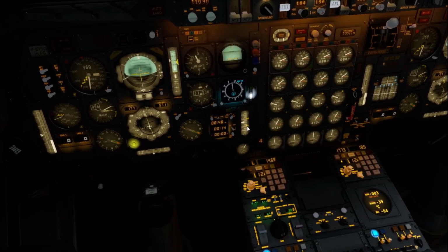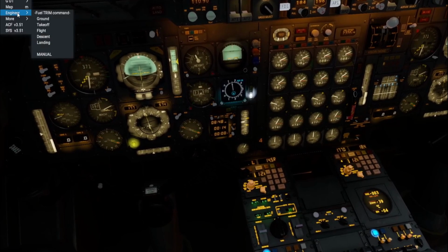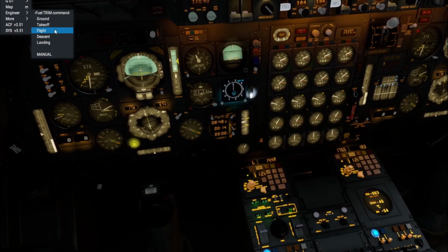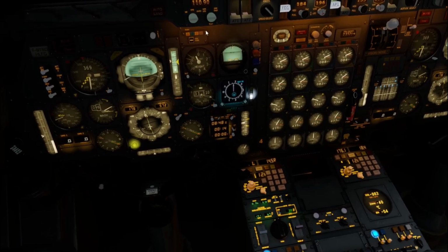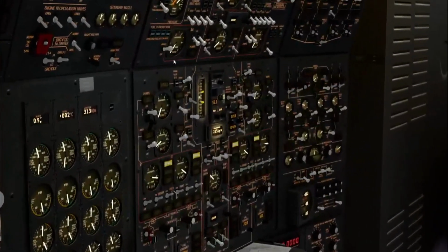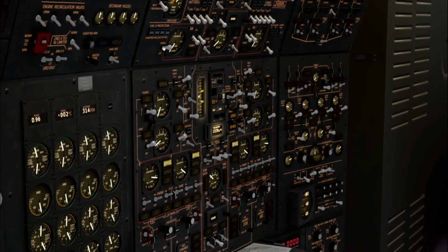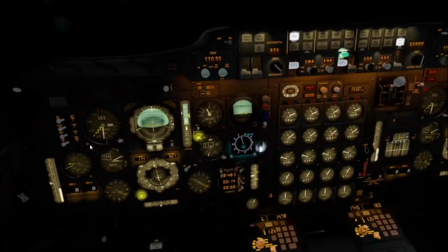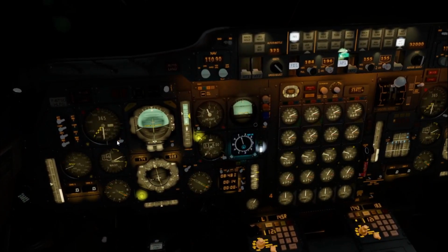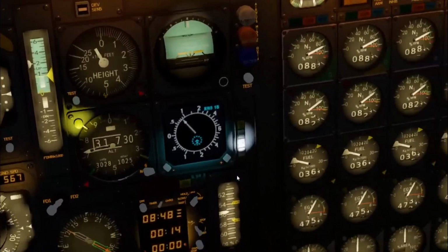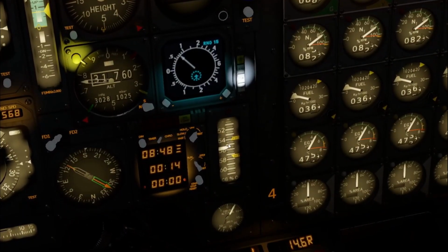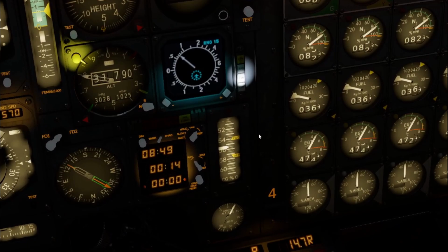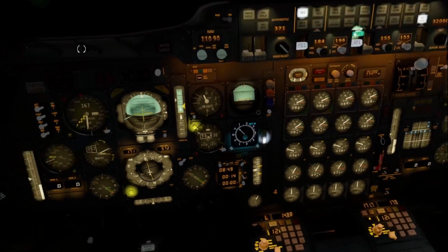If you want to go supersonic, you have to be in flight mode, which actually this one is set automatically in RTX package. If you have this switch on or armed, if you have it like this, it will switch according to situations to flight mode or trim. Basic is that flight, and you have to have 53.5, which we already have, but it's good to hear the call out. If you don't hear the call out, you have to do this manually from menu.